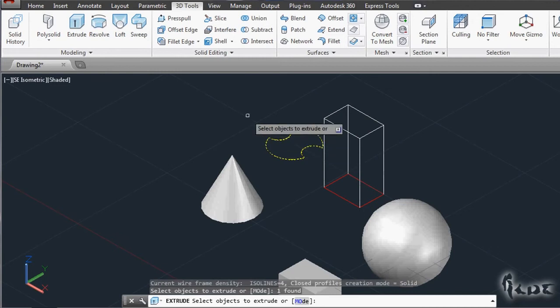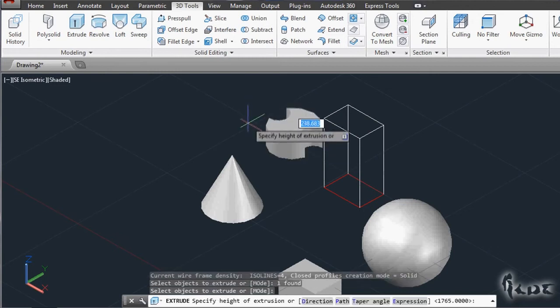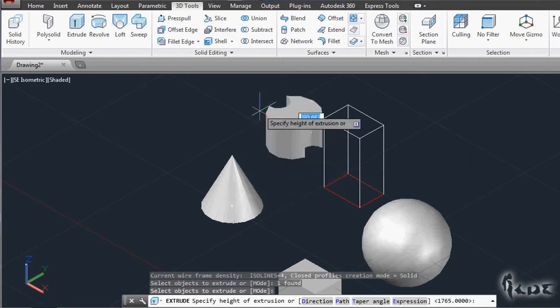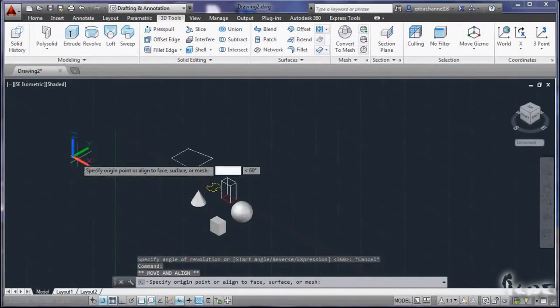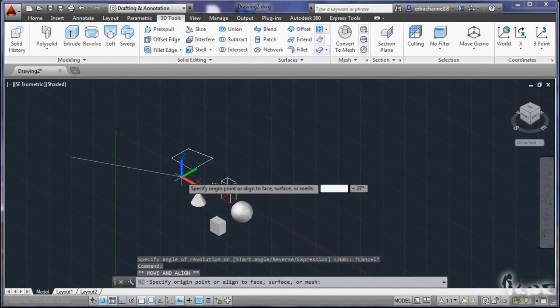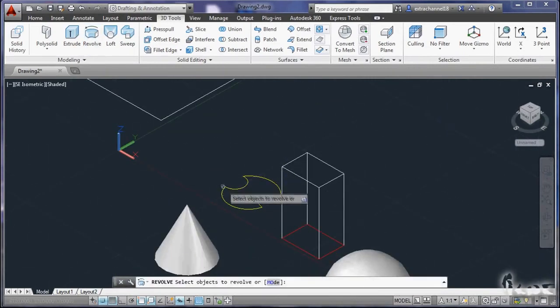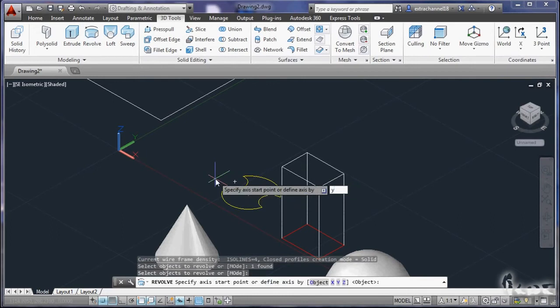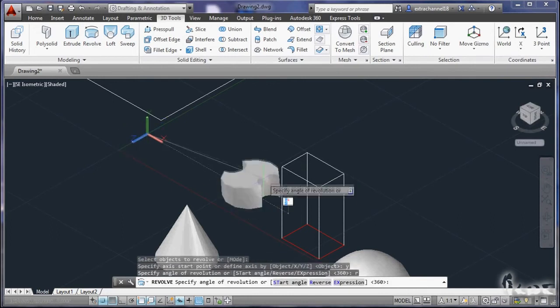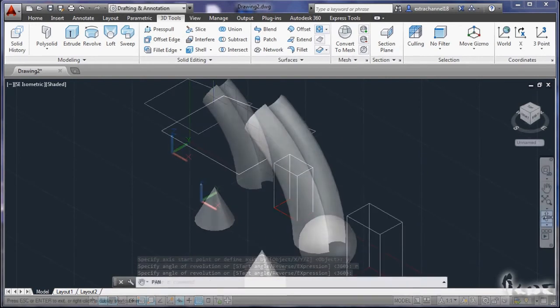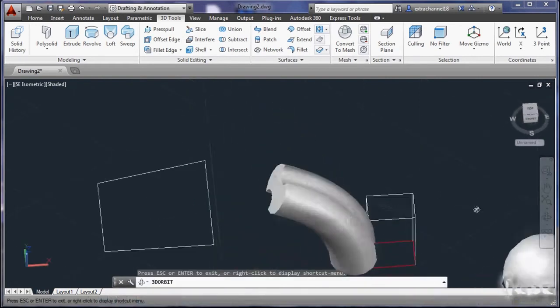After pressing Enter, you will see that the 3D is made simply by adding a vertical extrusion to the object, totally vertical. Similar is the Revolve command, which adds to a 2D base object 3D extrusion, but not straight through the Z direction, but changing angles according to the axis direction you can choose through the command line.